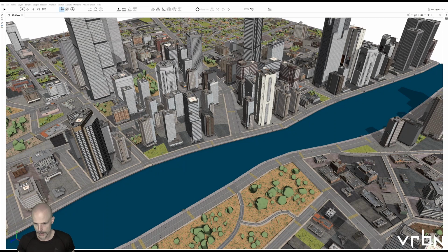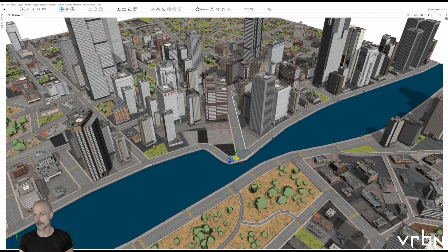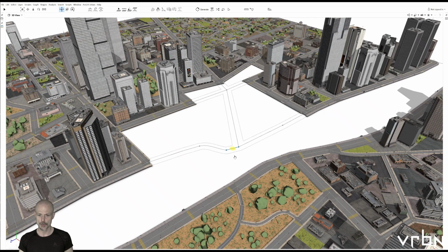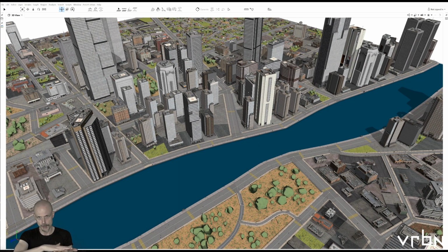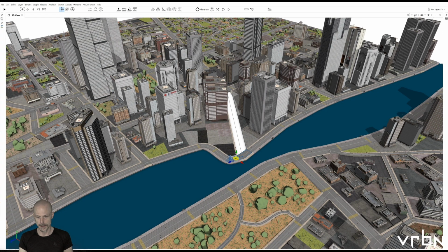Cool. So let's briefly talk about City Engine. We mentioned it at the very beginning. So how does it work? This is an older video I made some time ago, but it shows very beautifully that it has a centerline based system called dynamic city layouts that allows you to move and edit streets, make them wider also. And then the system actually computes the block subdivision, and then procedurally on top of those shapes, depending on if it's street shapes or lots, that means parcels, you can then assign different procedural rules to have the urban fabric generated.